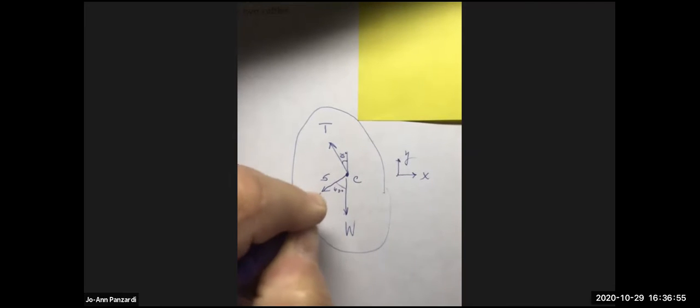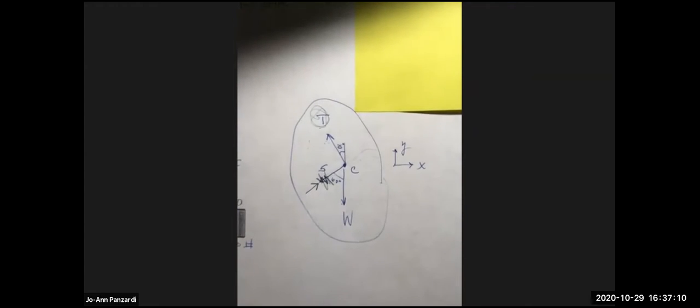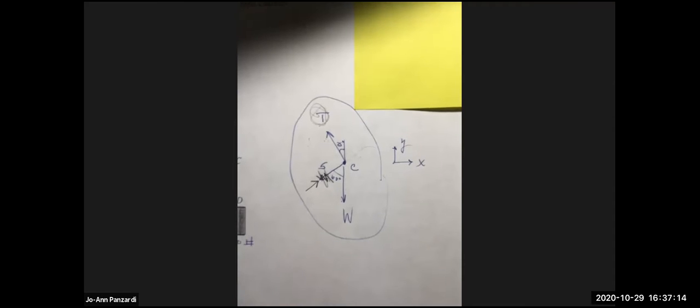Yeah, so it really needs to be drawn like this because we have a weight going down, and tension going up, yeah, that's okay. But the main reason is to balance off this T. The T is going to the left. I need to have something going to the right to balance this. Okay, that's very important. So I was just doing a little review, but my point really was, notice what this member is.